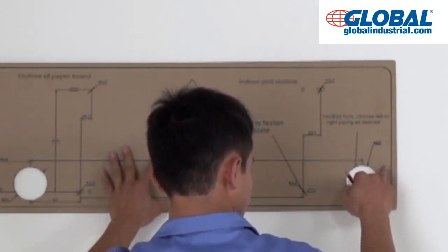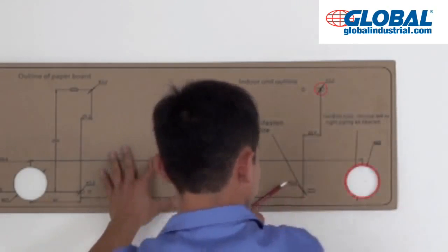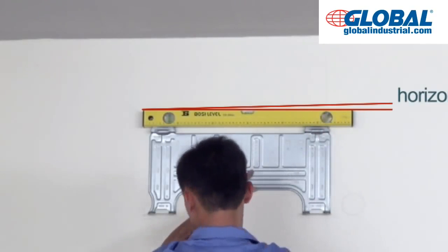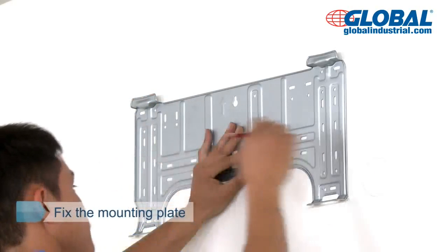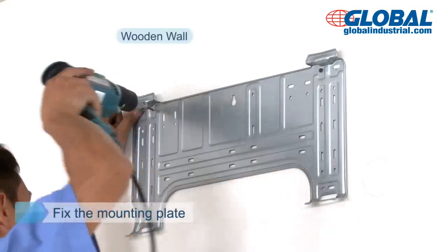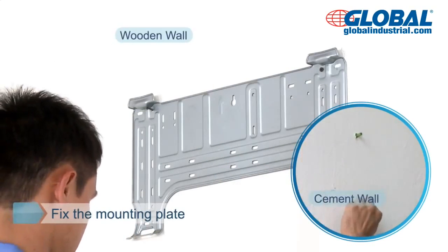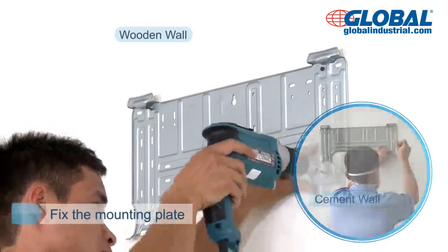Confirm the position of the wall hole and the screw above the wall hole according to the direction of exit pipe. Fix the mounting plate. Wall boards should be inclined appropriately according to the position of drain pipe. Align screw hole corresponding to mounting plate with the plotted position of screw, and plot positions of several other screws. Fix and install the siding after installation position is confirmed. If it is a cement wall, insert the plastic sleeve first, and then fix the installation plate with tapping screws.